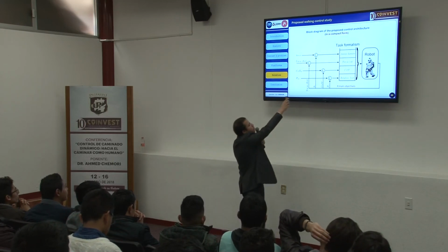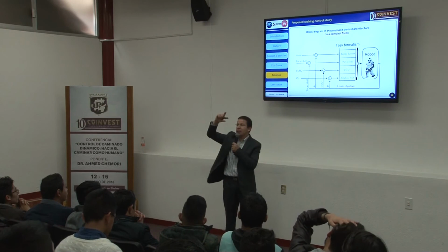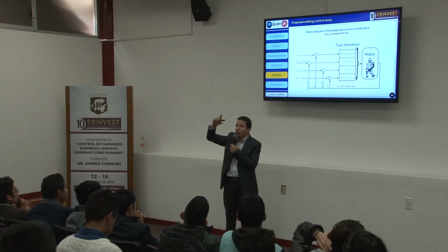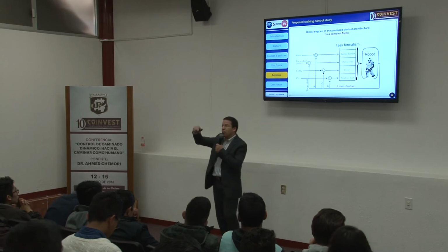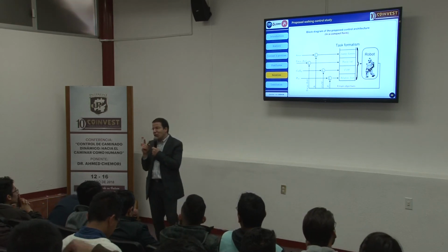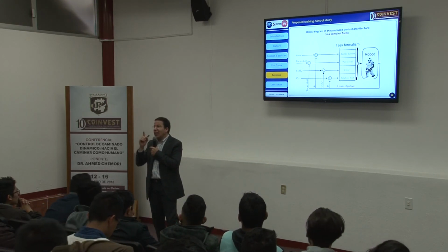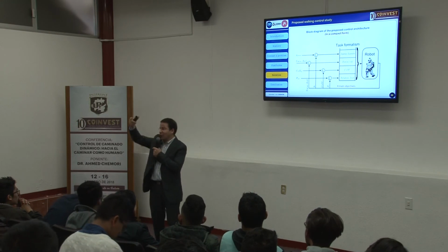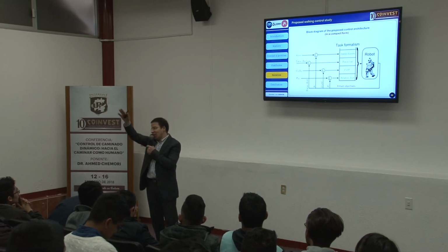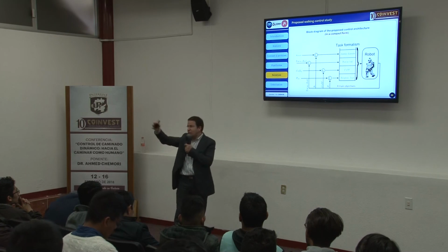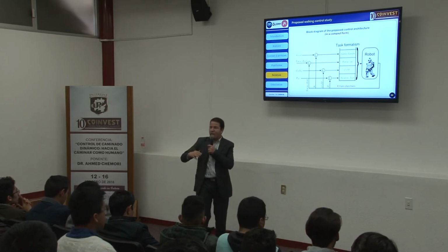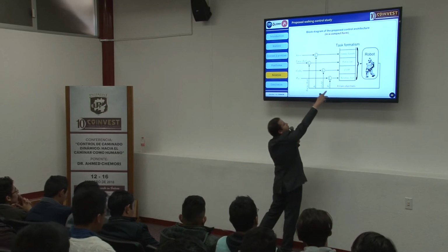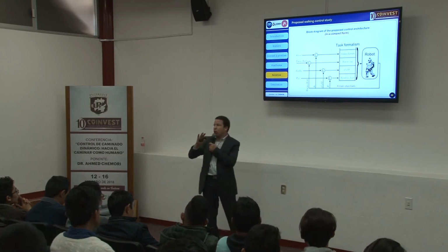We put the first task as the most important one, and then the second one, but when we put the second task, we have to avoid any conflict with the first by projection in the null space of the first task, and we do the same for all the tasks. So when we realize all the tasks, normally there is no conflict.